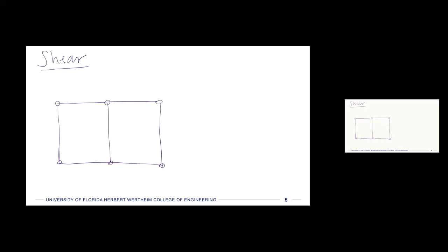And we can number them, and we can label some of these dimensions, right, like our equilibrium atomic spacing. And now instead of pulling on one of these along some dimension, we're going to shear across the top and bottom. So I'll draw a shear stress to the right on the top and a shear stress to the left on the bottom, and I'm going to label that tau. Right? Tau is the variable we often use for shear stress.